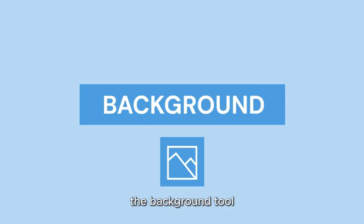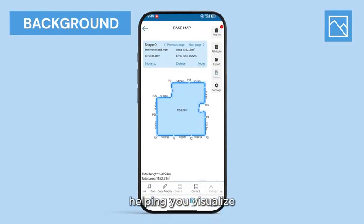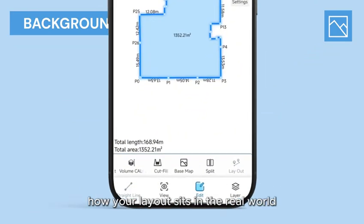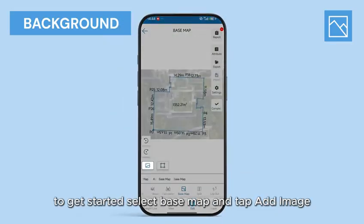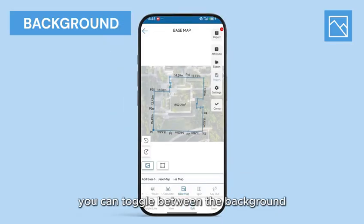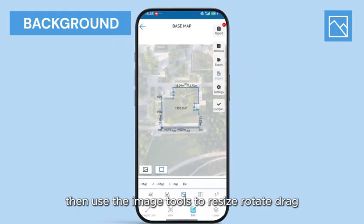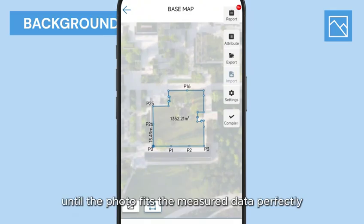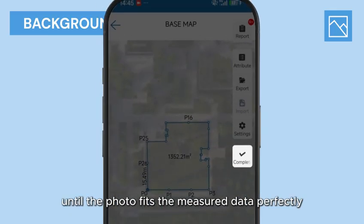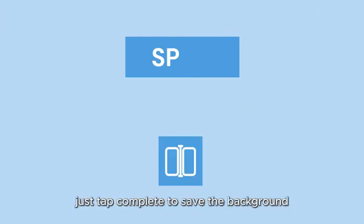The Background tool lets you add an image behind your measurement, helping you visualize how your layout sits in the real world. To get started, select Base Map and tap Add Image. You can toggle between the background and the measurement to help align them accurately. Then use the image tools to resize, rotate, and drag until the photo fits the measured data perfectly. Once everything is aligned, just tap Complete to save the background.